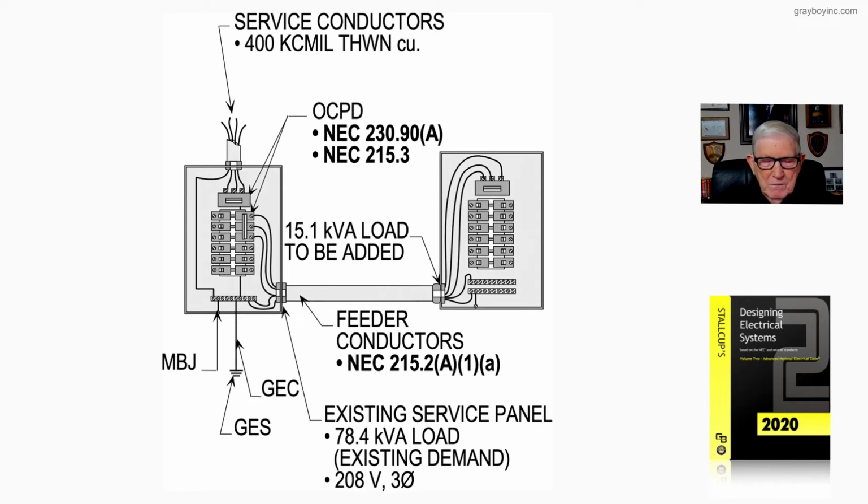For maximum existing installation shall be permitted to use an actual maximum demand to determine the existing load under any of the following conditions. So instead of the long standard calculation that we just looked at previously, they're going to let you size it off of a demand. So just kind of paraphrasing this exception, it's a lot of wording there.